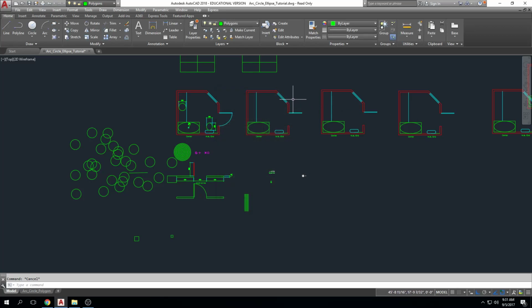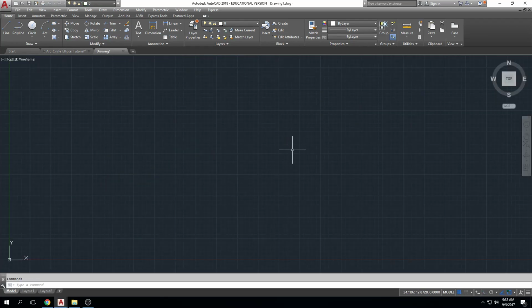The second thing is usually, and I say usually a lot because every now and again there's a weirdness that happens, but usually when you start a brand new drawing like this and it's blank in AutoCAD, it defaults to decimal. So you open up a brand new drawing. I can tell by having my coordinates on down here. Do you see how those are in decimal right now? 46.0209. I can see that those are in decimal.